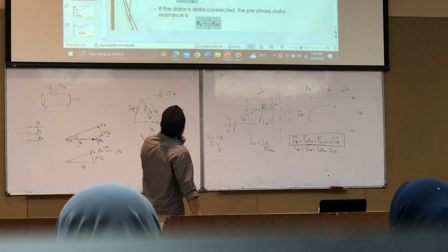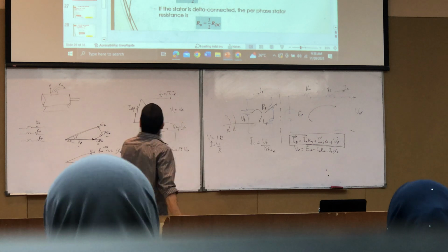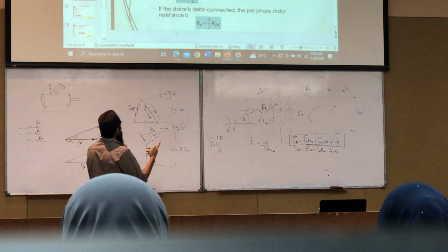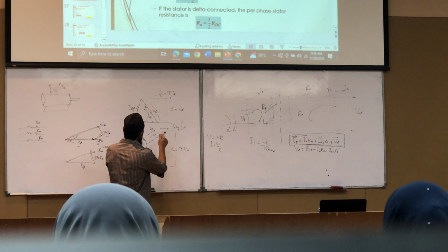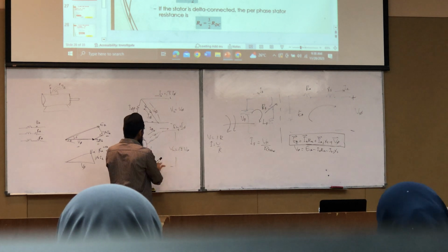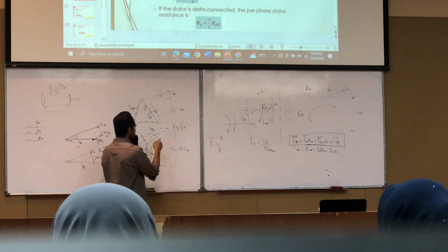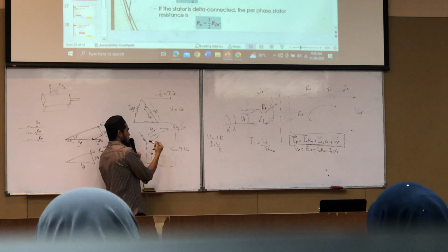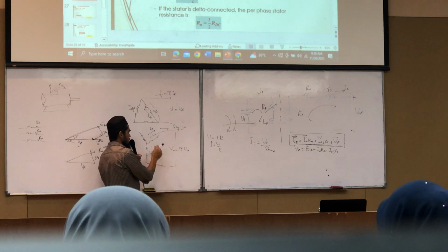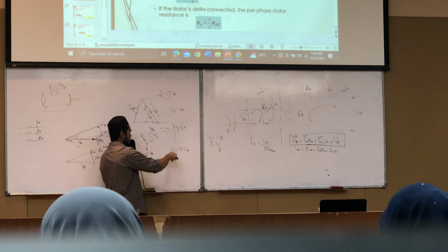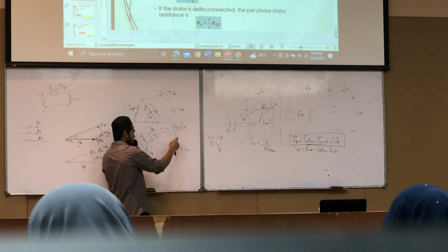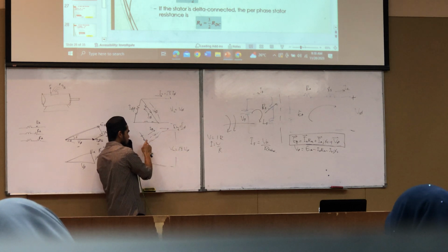For the DC test, I have explained inside the YouTube slide. We have to set either delta or Y. So we have indicated that scenario for our lab. We just connect in Y. So we put DC on the terminal, either from line to line or line to neutral.